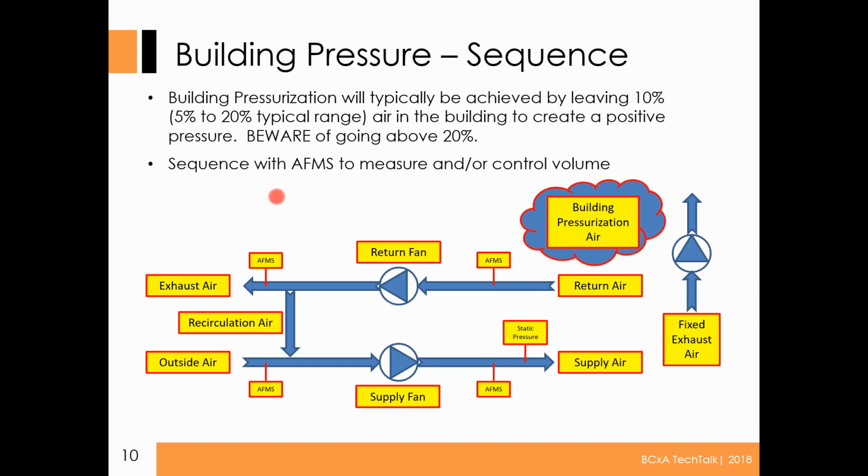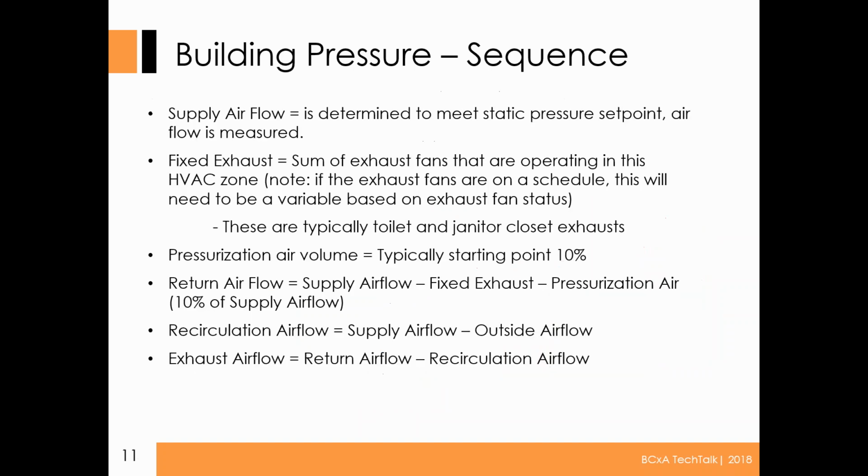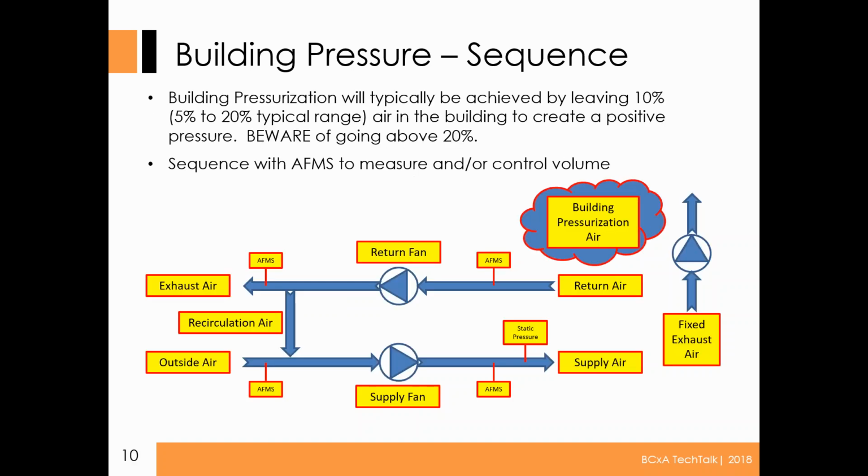And this is your kind of typical air handler screen. Let's dive into that a little bit more. Actually, I'm going to go back for a moment. If you have a project that's sophisticated with lots of air, these are your airflow monitoring stations. Some of our healthcare projects and some of our university lab projects will have lots of airflow stations, and they'll actually use the airflow stations in the sequence of operations.